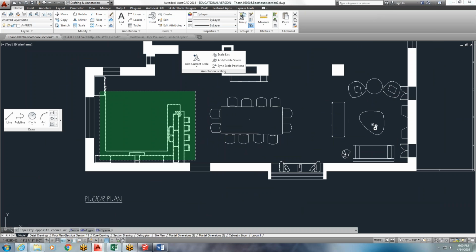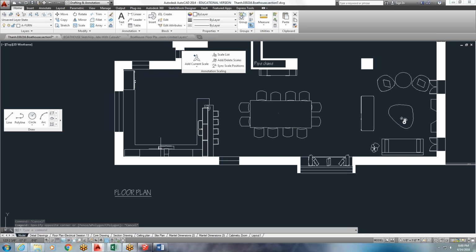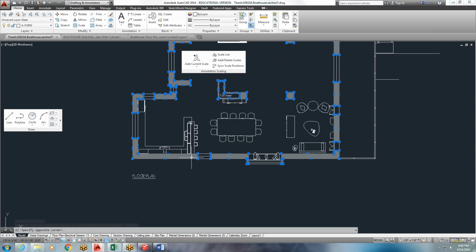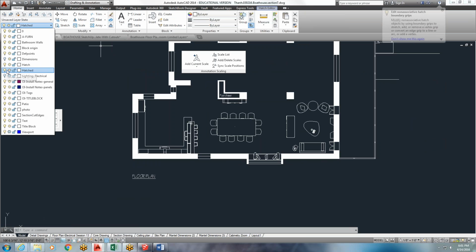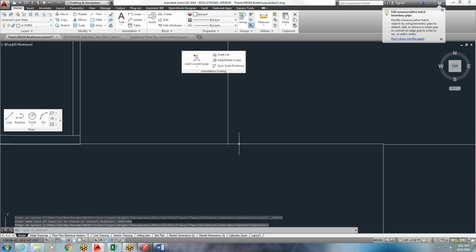But for the rest of you, what I've done is I started with this view, and then I actually turned, and conveniently, let's see, where are my layers? Way over here. Okay, so conveniently, Tan has done what I've asked her to do in past homework and put this on the hatch layer, so I can turn the hatch layer off, which will help me see what's going on back here and make sure that it's actually to the wall.